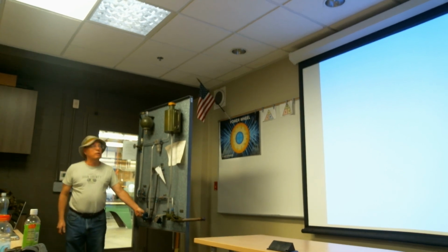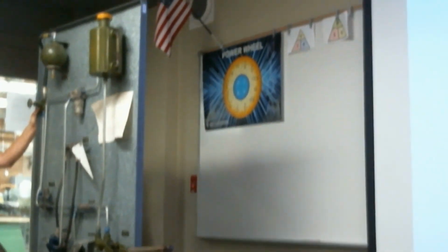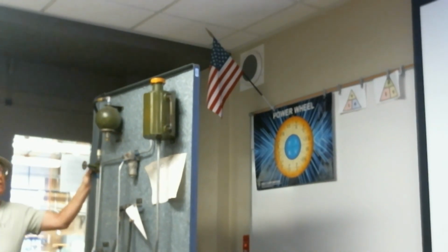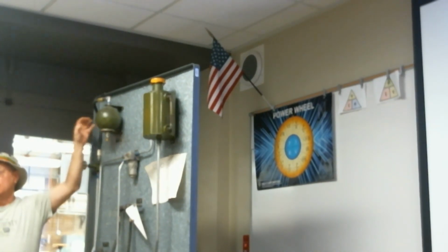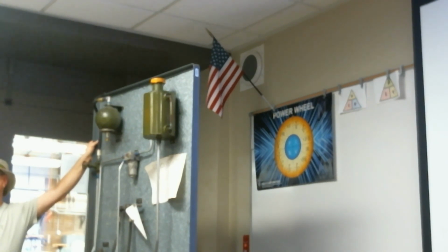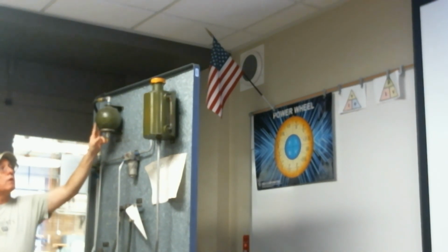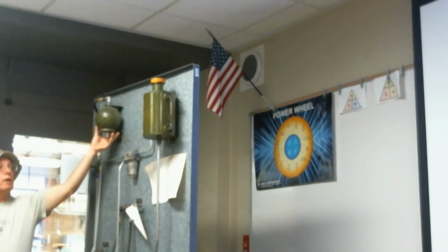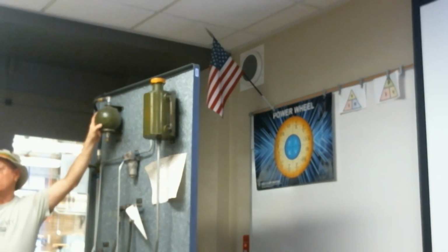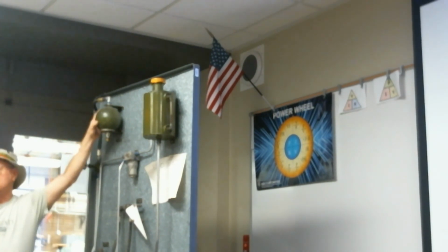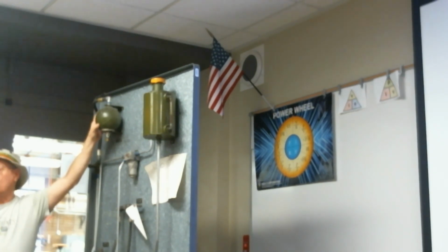Okay. So again, the system could be at whatever capacity is normal. Just understand that if you've built up pressure in the hydraulic circuit, and there's an accumulator in that circuit, the accumulator can contain that fluid, right? The other thing to remember as well, if you've lost the gas charge of the accumulator, the entire sphere of that accumulator will fill up with fluid. You may have whatever the system capacity is as being normal. It's just that a component has failed and it's holding that fluid in it, and it's giving you an erroneous reading on the reservoir. Okay? So far, so good? All right.